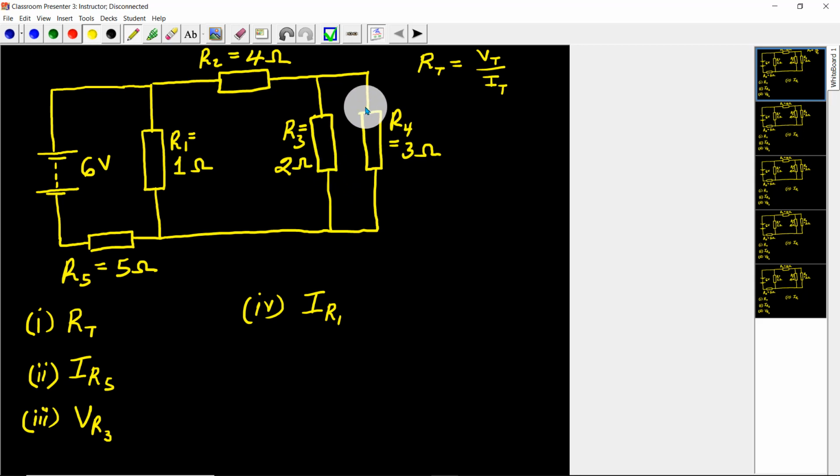Identify that small unit whose effective resistance you can get without it affecting or being affected by some other resistors. In this case, when I look at R3 and R4 and I look at the current which moves into that connection somewhere around here, it splits at this point in this direction and in this direction.